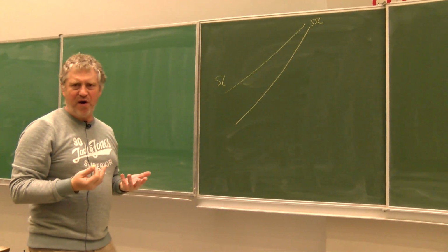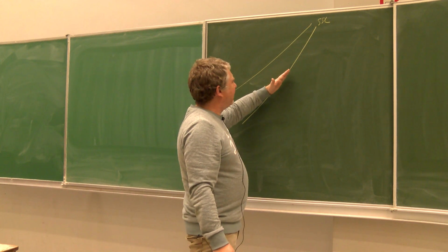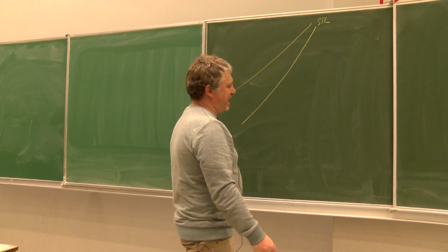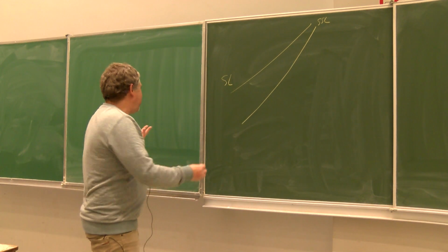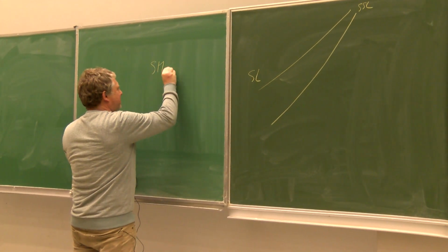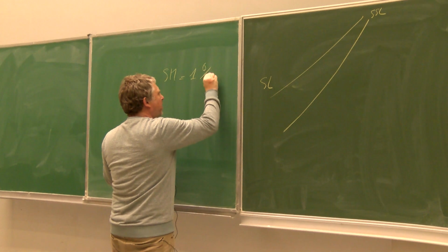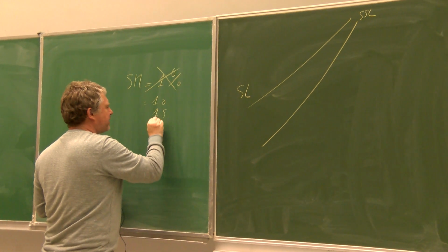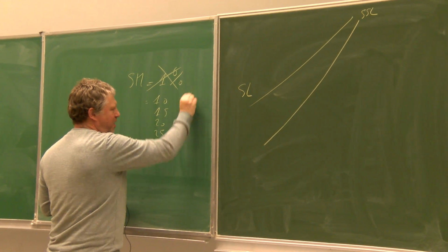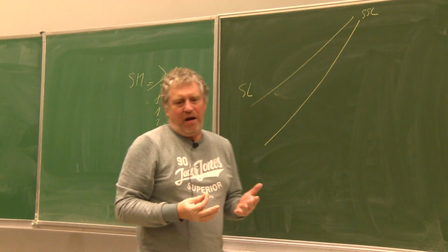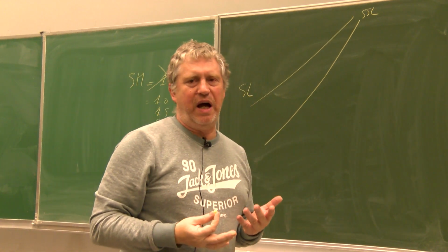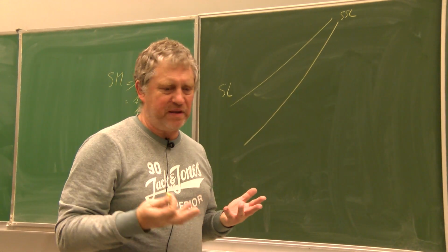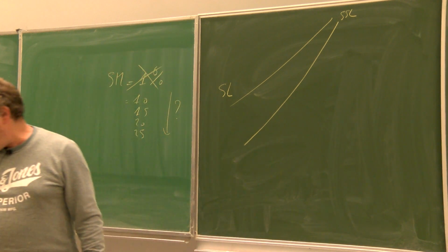Because it's a loss of performance. You could raise the steady state line so it's going nearby the surge line. So the question is, why is not the surge margin equal to, let's say, 1%? Why is it not the case? Why are they going to 10%, 15%, 20%, 25%? Why is it so large? And this is, of course, related to a certain loss of performance. It's very clear.